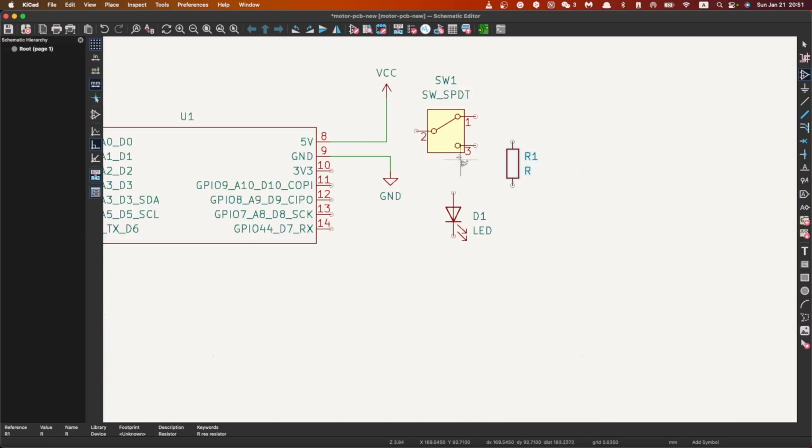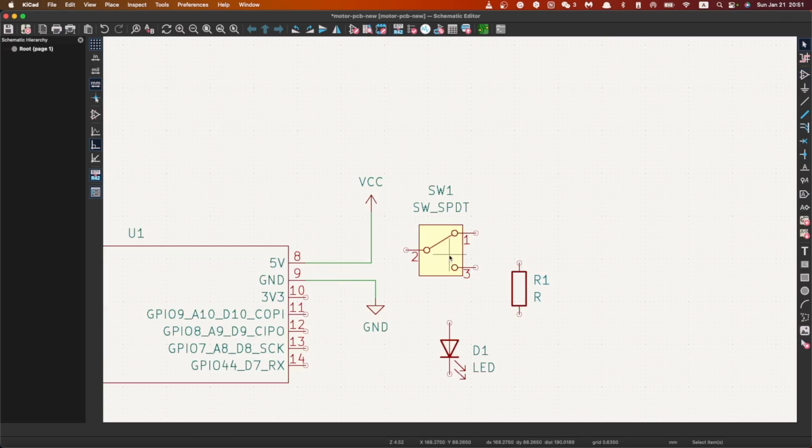Right. Okay. So now I'm gonna introduce several short keys or shortcuts for KiCAD for manipulating these elements in your schematic. The first one is pretty simple, which is move. After selecting an element here, and be sure you've selected the whole element instead of just the font here.